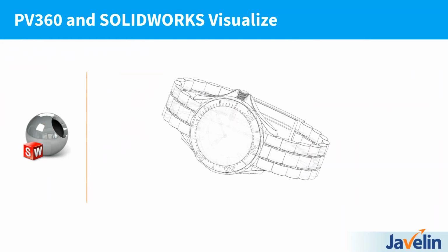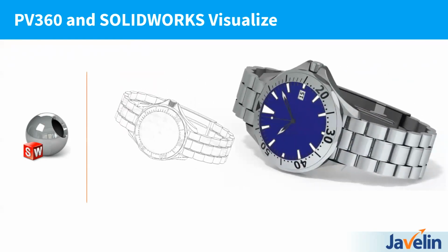And not only that, sometimes you may have different finishes, you may have 4 or 5 different options, and you want to be able to see what it's going to look like in those different options relatively quickly, but you might still be in prototype stage where you're not ready to really put together that marketing material. And that's really where PhotoView 360 is so handy, because it's built right into SOLIDWORKS. You can have the different display states with the different materials applied, and you can quickly render those out, show them side by side, so you can see right away what might be good or bad about your design visually, right? And not only that, it gives you that level of depth that if you're not really good at visualizing the CAD model, it comes with all the shading and all the shadowing and stuff like that to make it look a little bit more realistic.